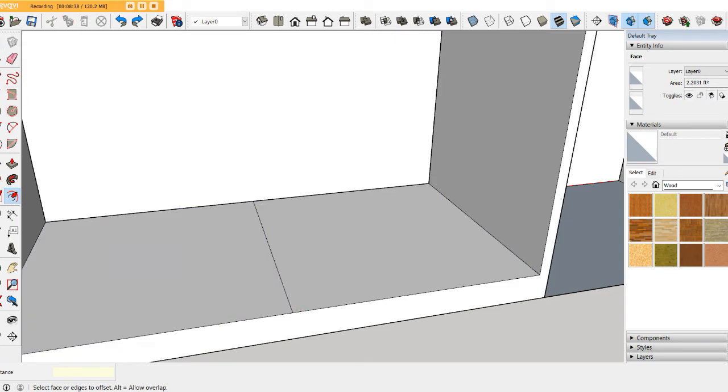What I will do is first I will select this line, then I will offset this using the offset command over here, and it will be like 0.75 inches. So I don't know why it's not taking it, or what else we can do is just copy this line, select this line first, then use the move command, control, from here to the edge, we will make it 0.75 inch.